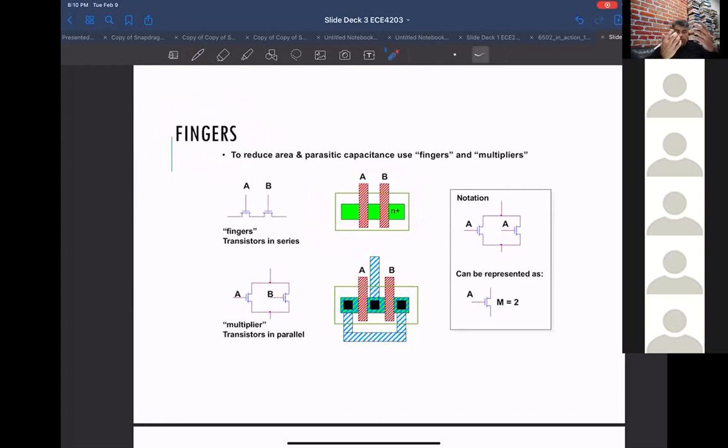You can actually overlap the layout of transistors because, for example, let's take this case. You have one transistor in A, one transistor in B. You don't need to contact this active point, it's the drain of A and the source of B. So you can think of it as just one thing. You'll never need to electrically connect to it. As you'll see in the CMOS logic, you won't be putting a contact here.